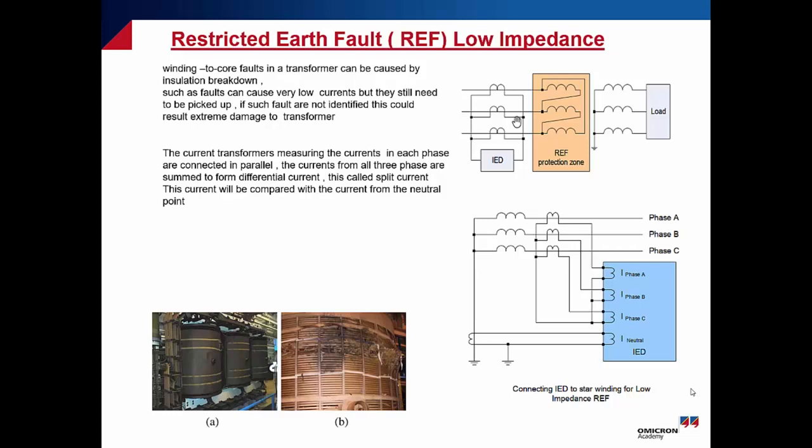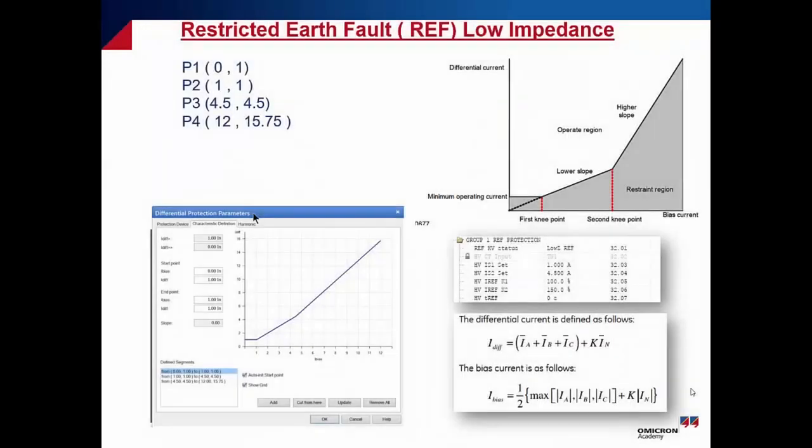How to test it? Actually, we have different techniques. With Omicron, I can count three different techniques. Technique number one, we can use single phase differential. If you remember, we have a single phase differential test module. You can use it, but be careful because it is supporting this bias equation, not applicable for any relay. It's applicable for MiCOM P6 and X series.